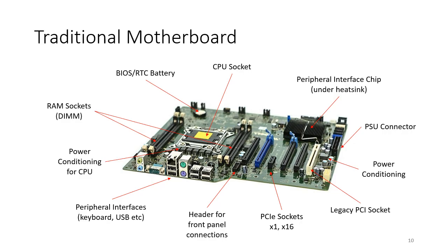Now this particular motherboard, moving around to the right again as we go anti-clockwise, it's also got a legacy PCI socket. So this is an older version of PCIe, of PCI rather, and this is used for older versions of boards. So you might see that in industrial PCs, but I would say these days you're probably not likely to see that unless it's a specific computer board that is designed to have that PCI interface for legacy boards. These days most things have migrated to PCIe. So PCI, you can see it's got a different format. It's a slightly bigger connector. It certainly doesn't have the same level of throughput, but you might see that on some legacy devices.